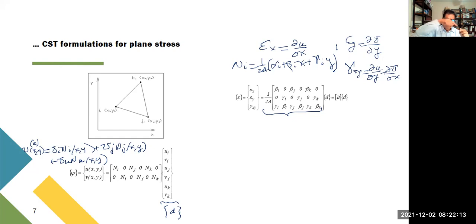In between these 3 joints, we assume the interpolation. That's a linear interpolation. What happens if the exact solution is not linear, it's not a flat little surface? Error. So we have to make these elements as small as we can so that the error is small. That's the idea of the convergence problem.